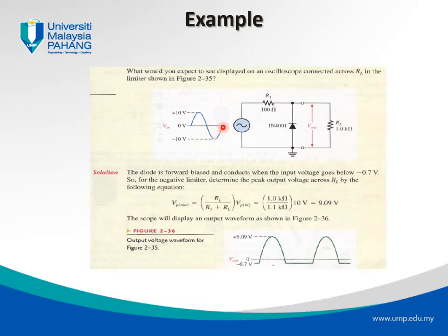And as the input goes to the negative half of the waveform, now the current will circulate in this direction where the diode is in forward bias. When the diode is in forward bias, the current will circulate as a short circuit in the inner part of the circuit. So no current goes through the load resistance. When no current goes through the load resistance, we won't observe the sinusoidal waveform at the output, right? That's why we have this flat part of the output waveform.